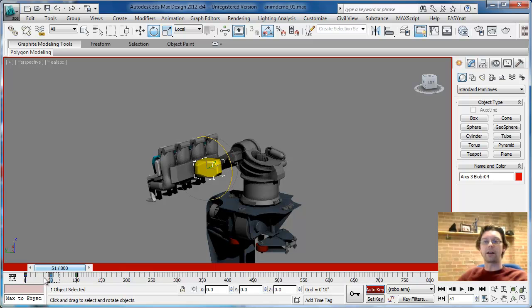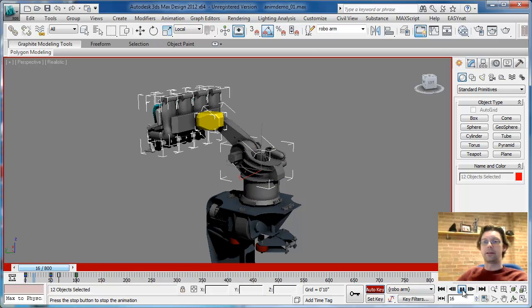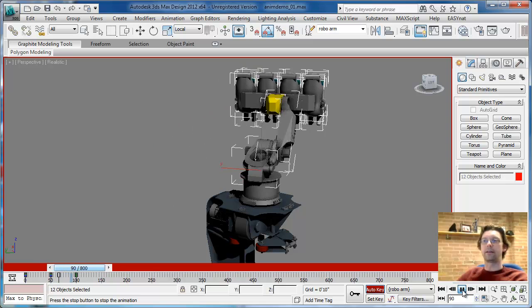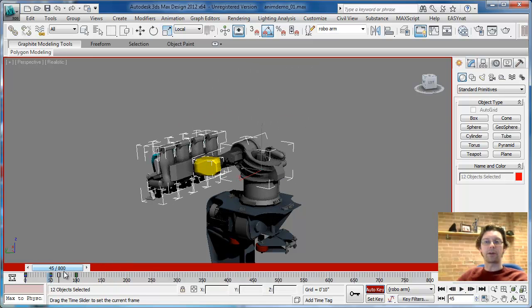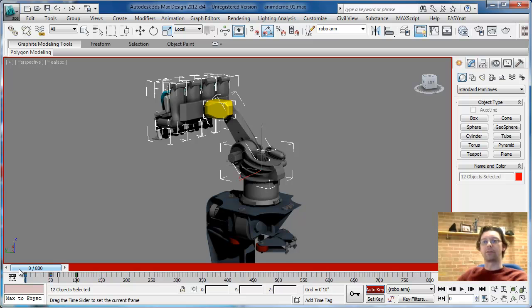So if I go down here and just select all the frames at frame 50. To do that, I'm going to select all my objects, so I make sure that all the objects I'm animating are picked. Do a little selection fence around this keyframe, and now if you hold the shift key and just drag it over, say 14 or 15 frames, and let it go, you've now duplicated all those keys. And now if I cycle back and hit play, you'll see it cycles down, holds for a bit, and then moves. So I've created what we call bracketing of that position, so it's forcing it to stay the same for a little while.